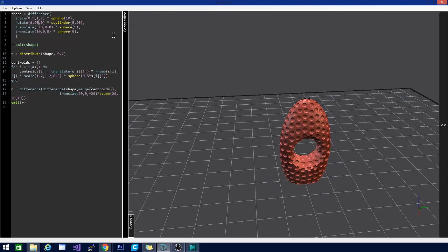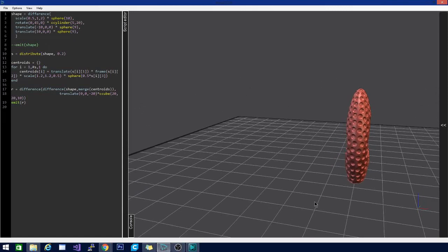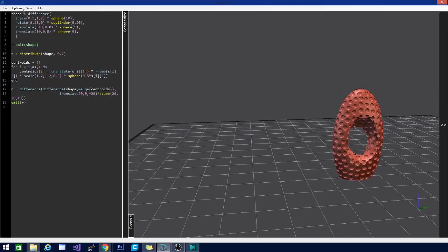You can see exactly how this shape is done here, and you can actually change the cylinder. Okay, so I take this cylinder to 45. You can see it changes the shape in there, and it's putting it in at an angle, so it's passing through like this instead of at a 90-degree angle. So basically what they're doing is they're declaring their shapes, and this is a shape called difference, and it is actually an array of shapes inside it. So there are 4 different shapes inside this array called difference, and then it's going to basically put them in right here by saying R equals difference, and then emit R.